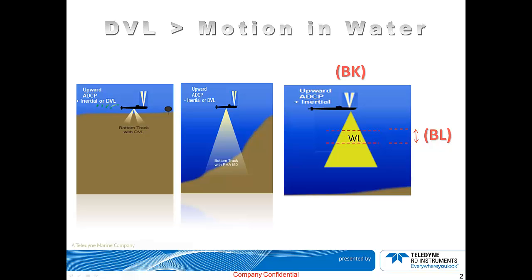This is so they can avoid strong water currents and thus minimize possible bias in the data. Some users put it close to the vehicle for some reasons, but when doing this, one must be very careful about the effect of water drag as caused by the vehicle. For example, if the ROV drags the water in a similar direction to where it's heading, obviously this might bias the velocity reading to 0.